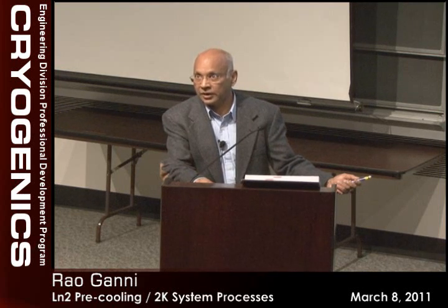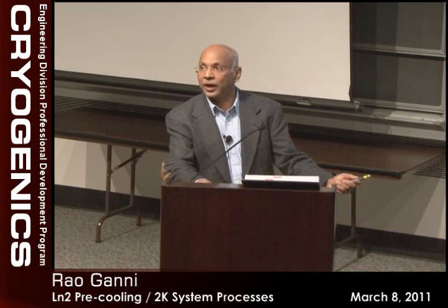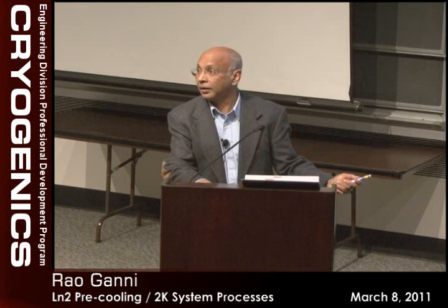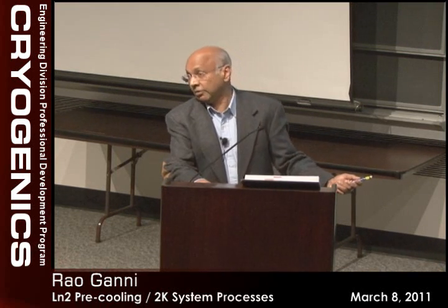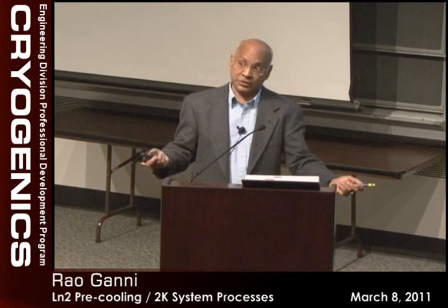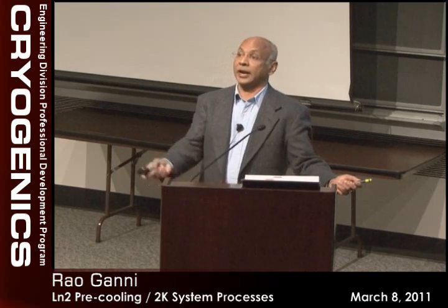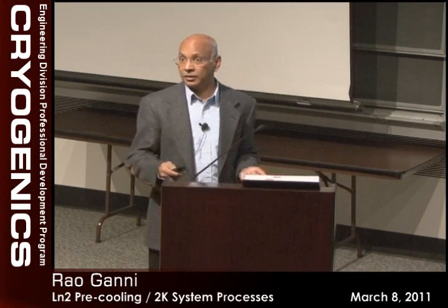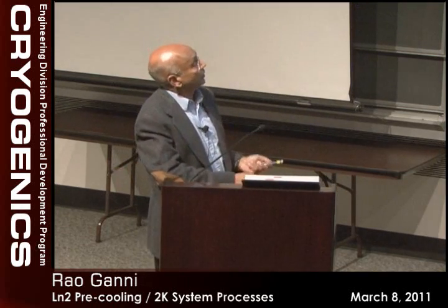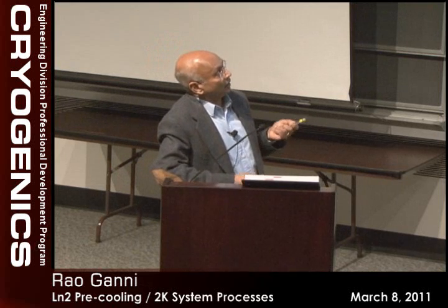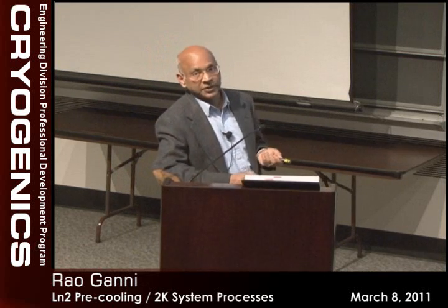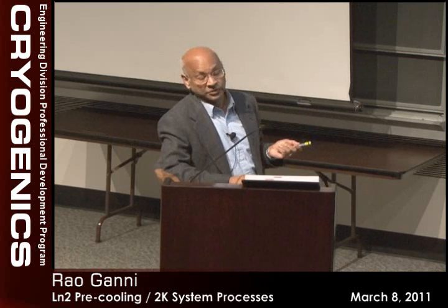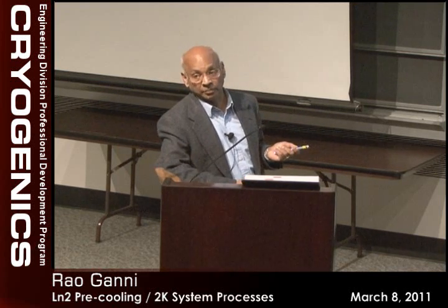In my opinion, compared to the disadvantages of the hybrid, people should really look at whether we can do everything the cold compressor way and get the range. Even if we get 50%, that may be sufficient. 60% may be sufficient compared to the other headaches of room temperature and subatmospheric components that come with that. If you use the same cold compressor efficiency, because of the heat exchanger losses and warm compressors, it will not be as efficient as all cold compressors.